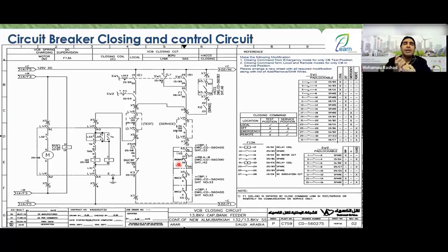Regardless of the type of protections, whether it's main protection 1 or main protection 2, and you have busbar protection, if there's a fault on the bus bar, it disconnects the capacitor bank. And in the case of breaker failure, when my cell has a breaker failure, I isolate the bus bar. At the same time, I prevent the reclosing of my other breaker until I fix my fault. Even when I fix the fault, what fault am I following?